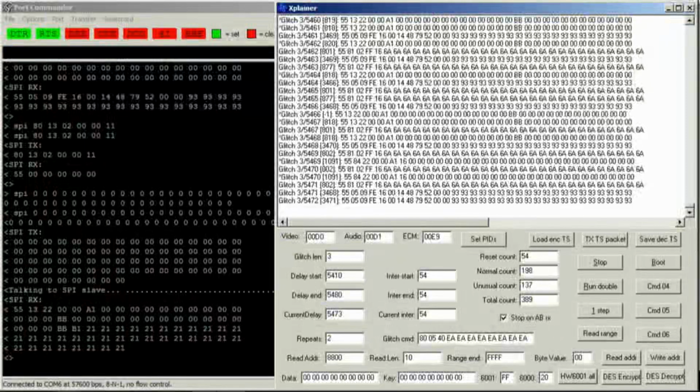So I wrote a simple application that performs the glitch searches and then can interact with my code payload backdoor I've installed in RAM. This program allows me to enter an address and length and have data returned or to write to memory, etc. There's also support for setting the key and data and performing DES encrypt or decrypt using the hardware peripheral inside. At this point, I noticed a few points about this chip.